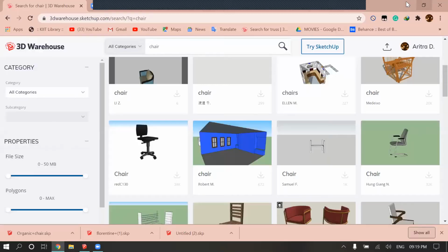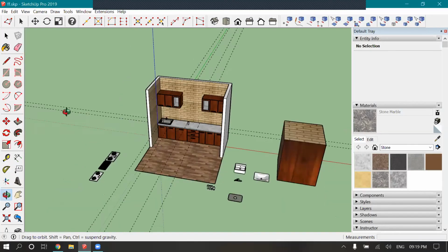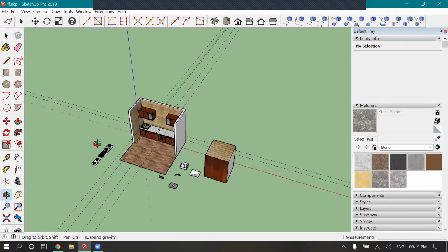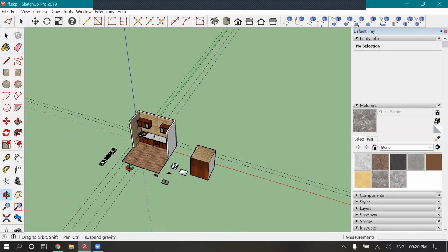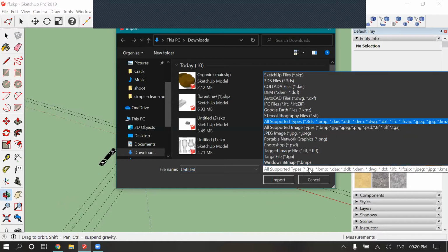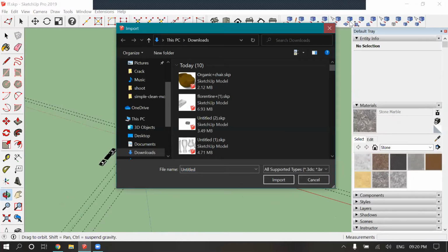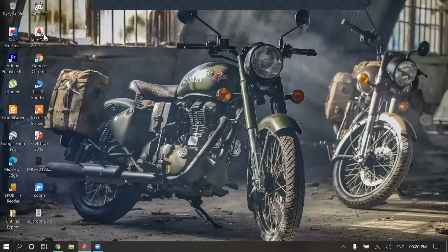Today will be about how to start any project all by yourself. So you need to import your AutoCAD file from AutoCAD, but the format will be a bit different, because in the import section the type is DXF. You need to save it in DXF format.